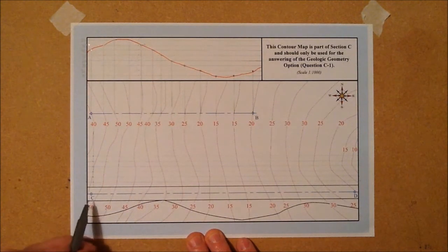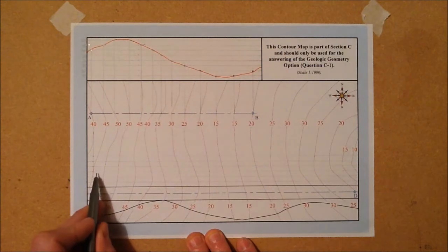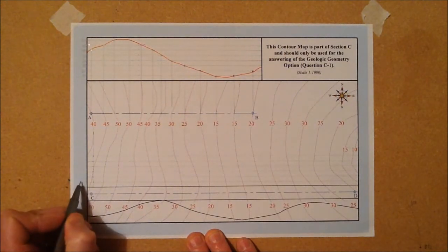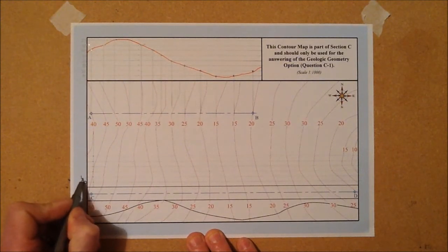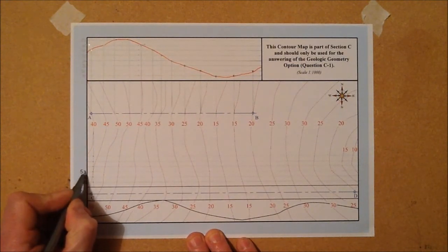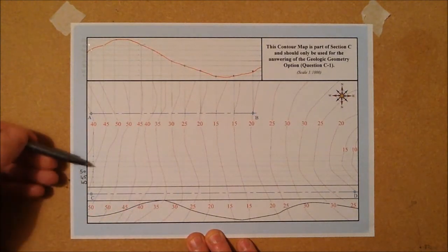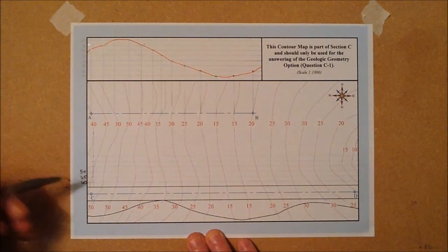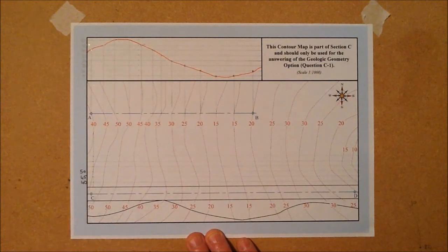Okay, so just getting back to the labelling again, if this point here of the road is at 35 metres, I'm going to label these intervals in which I've marked out, as we know the land is rising, so I'm going to go in 5 metre intervals. So this first one is going to be 40, 45 metres, and 50 metres is the highest one. Now I know I have a few extra lines going here, but that is not necessary. Okay, so it doesn't really matter as long as I have the ones that I require for the different heights.